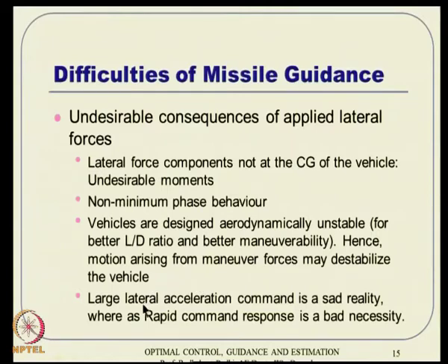And also remember that large lateral acceleration command is a sad reality. That means the targets are becoming more and more powerful, they have more and more maneuvering capability. So we do not have the luxury anymore not to have large lateral command acceleration. These modern day missiles, especially these defensive tactical missiles, have to have large lateral acceleration. For example, some air to air missiles talk about 20-30 G of lateral acceleration, which is quite large. So that is a sad reality, whereas the rapid command response is a bad necessity also.